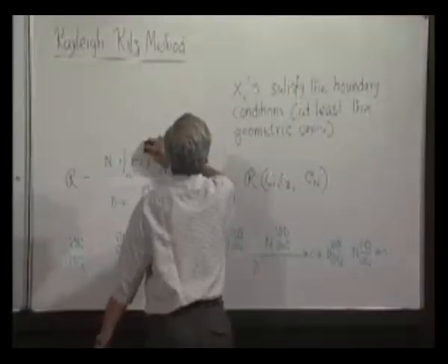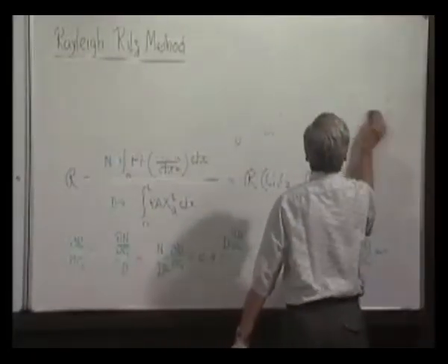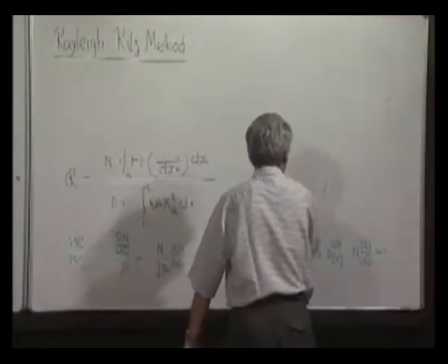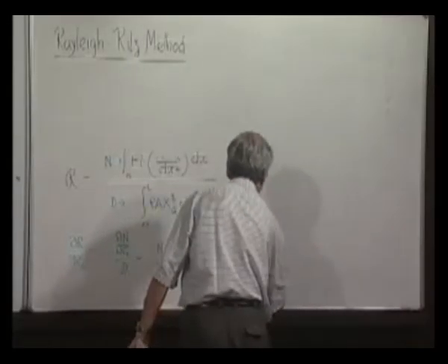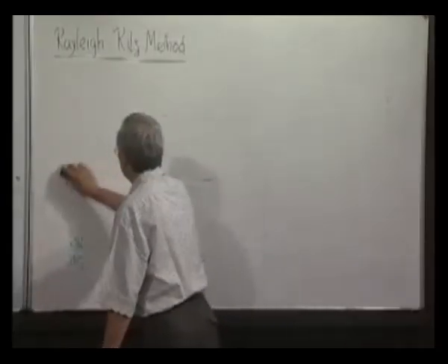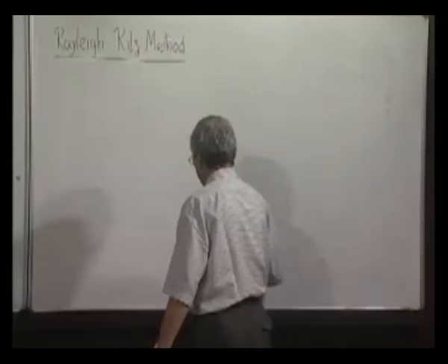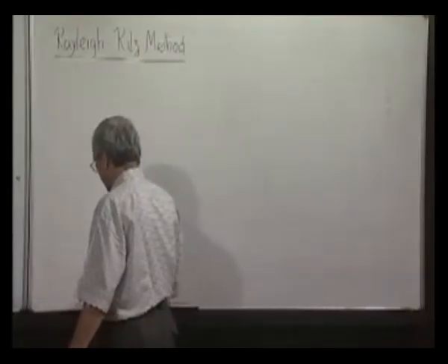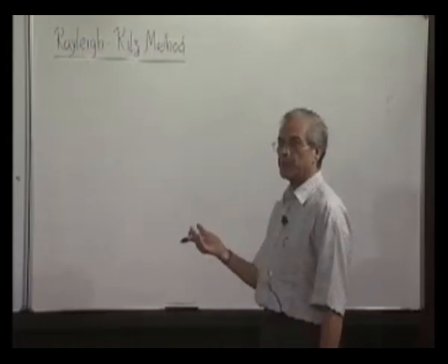We have found out the fundamental frequency by Rayleigh's method, with Grammel's modification. We also know the exact value. So it will be easier for us to assess our answer which we get from this, at least the first mode.